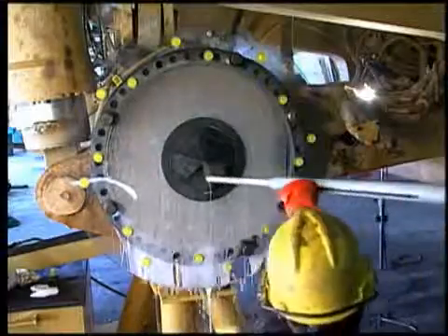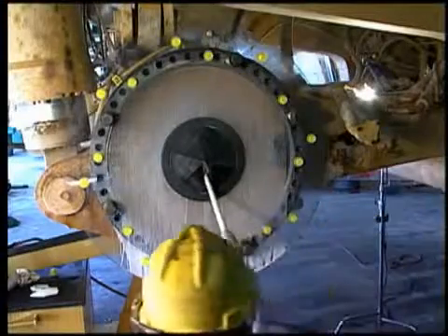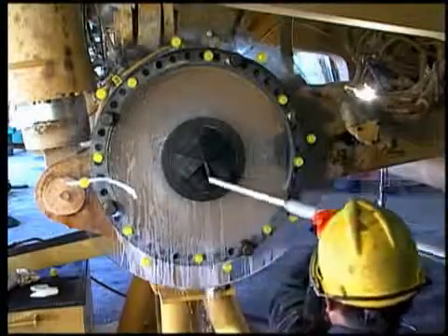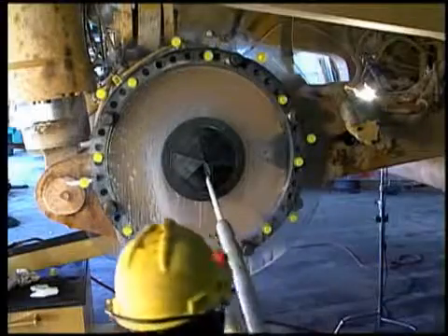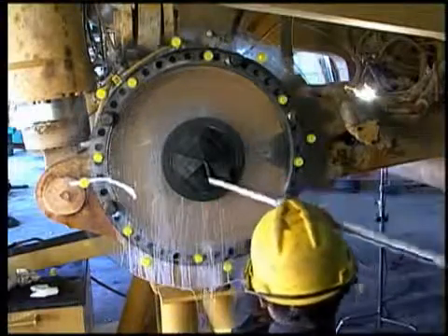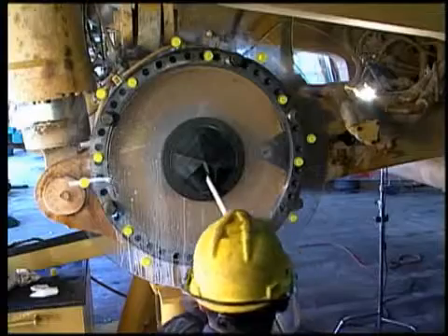If the differential housing isn't properly cleaned when new or rebuilt final drives are installed, the remaining contamination in the housing will contaminate the final drives, causing leaks and premature wear.